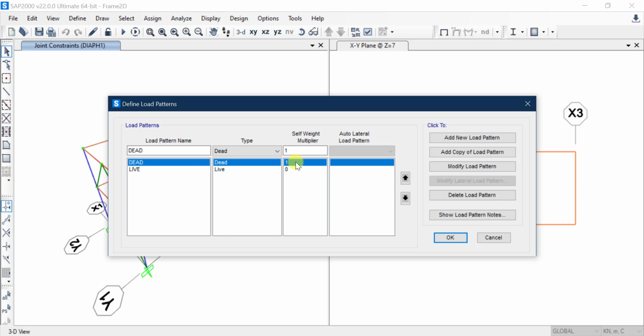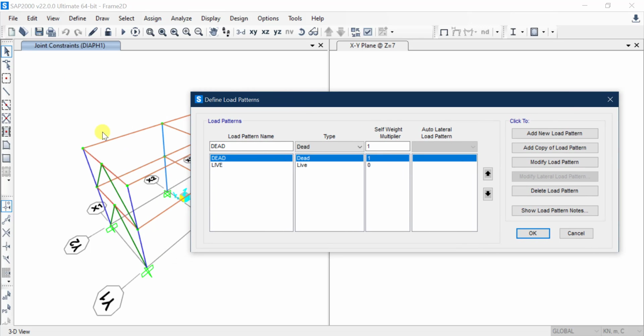Because in some cases, especially if you are designing a structure and you're doing the first iteration in your design, you put some random or approximate member sizes into your model, and then you conduct the analysis, and after you conduct the analysis, you design the members, and then you assign the designed members again, and then you do another analysis. So it's kind of an iterative process.